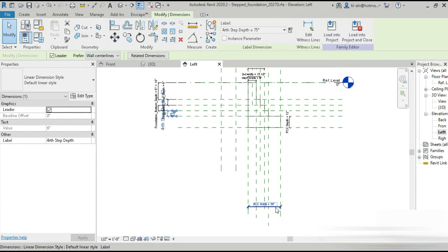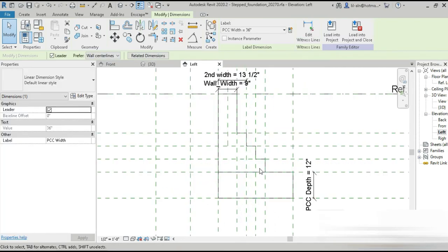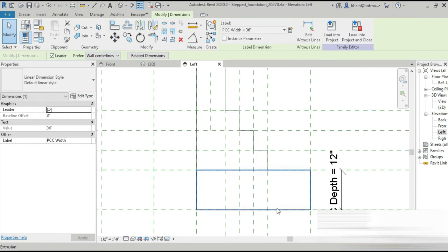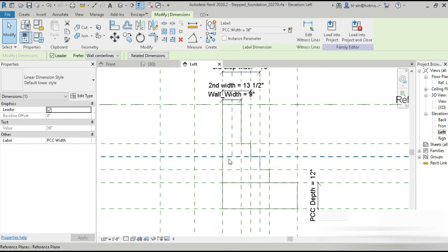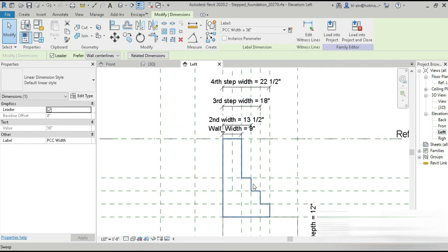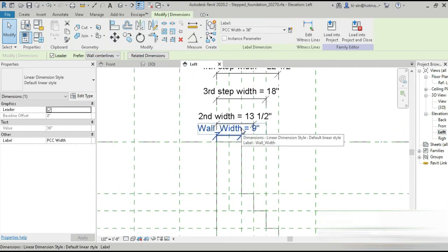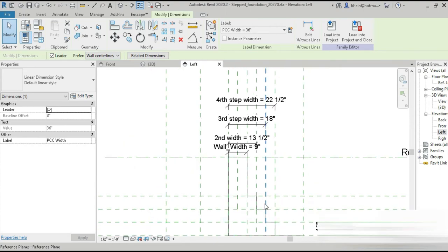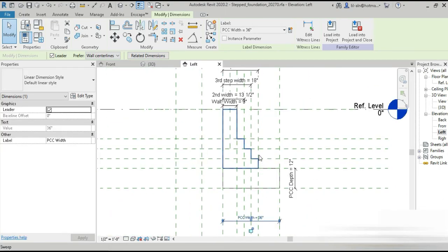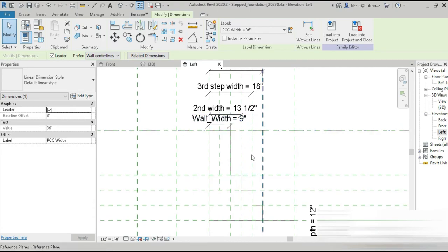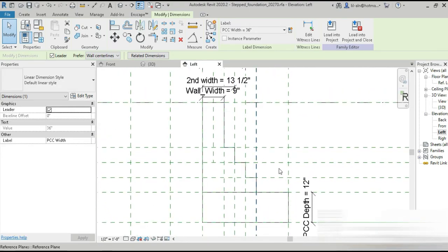So now we can say that we're completed already. And check this out. This is the exact same thing. It's the load bearing wall foundation, but it's slightly edited because there's another house located on one side. It means that these bricks have to be shifted to that side. And overall, the concept is the same. The first one is 9, as you can see. The second one is 13.5. The third one is 18, and the fourth one, as you can see on the top, is 22.5. So there's an increase of 4.5, which in this case is going to be 2 bricks.